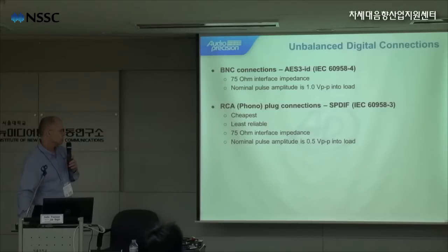So these are the cheapest, the least reliable cables. They have a 75 ohm interface impedance and a nominal pulse amplitude of 0.5 volts peak to peak into the load.